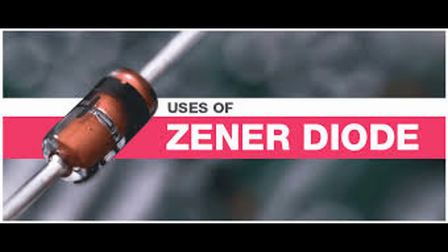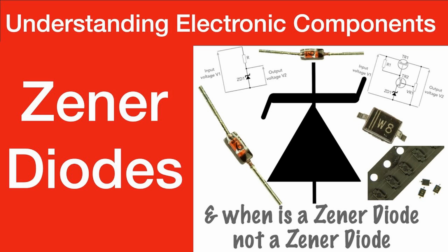1. Voltage regulation. Power supplies. Zener diodes are used to provide a stable reference voltage in power supply circuits. They maintain a constant output voltage despite variations in the input voltage or load conditions. Series regulator. In a simple Zener diode voltage regulator circuit, a series resistor is used with the Zener diode to drop the excess input voltage and maintain a constant output voltage.